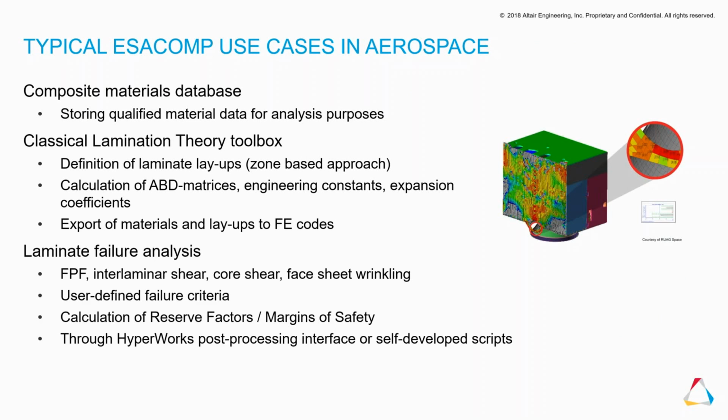The ESAComp failure analyses are extensively utilized in design validation. So the FE solver and its post-processing capabilities may not be what the customer needs. For the detailed stress reports, ESAComp may help in getting the reserve factors and margins of safety, for instance, with a given failure hypothesis presented in a way that's more suitable for the customer's purposes.